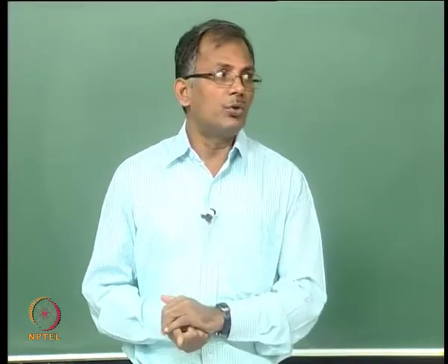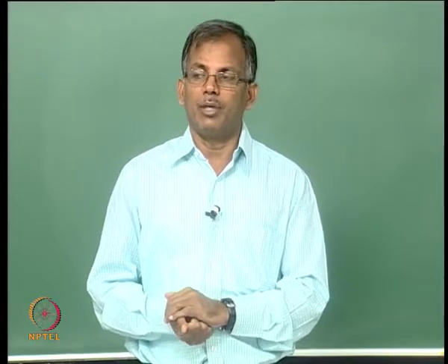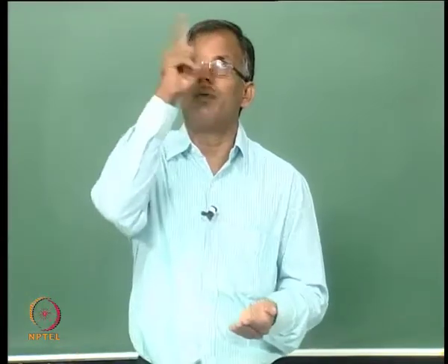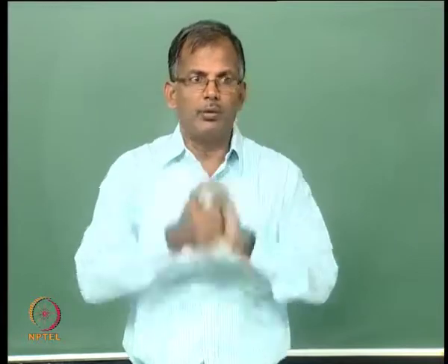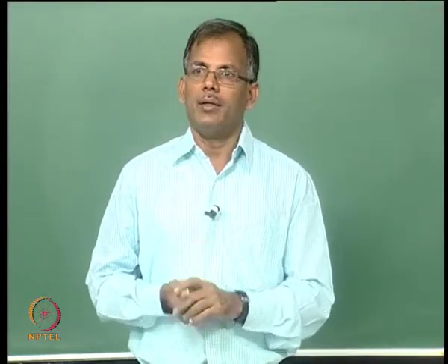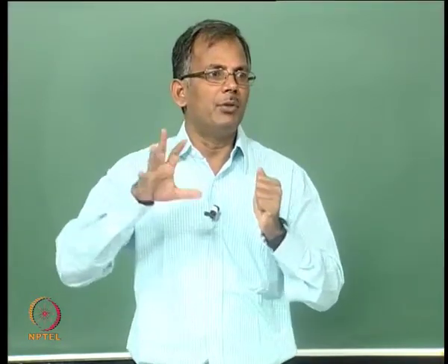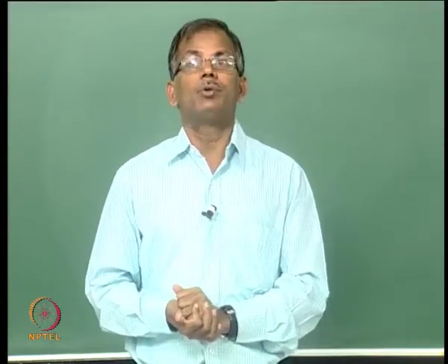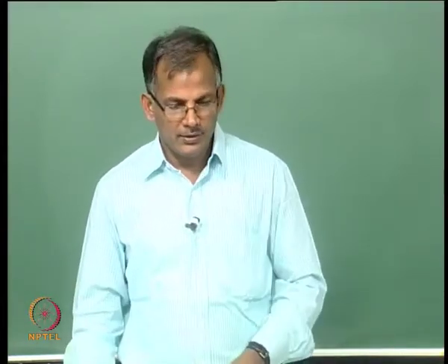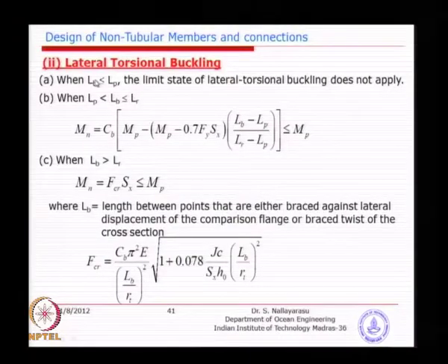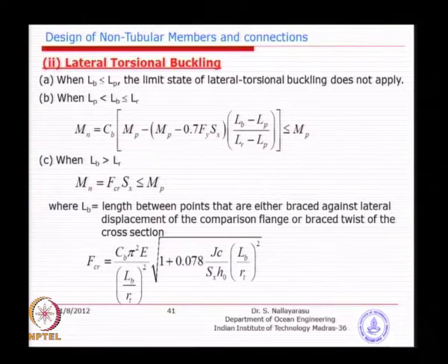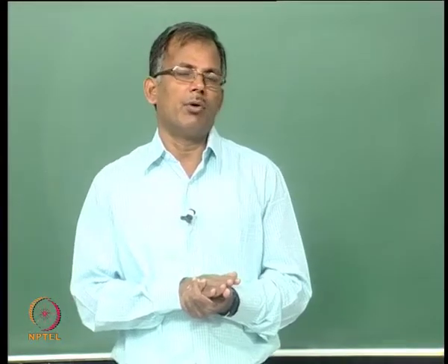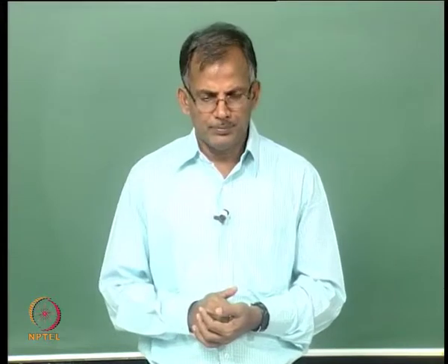That will be the case in most of the deck structures in offshore, because you put one big deck plate, like a floor plate, and weld the floor plate to the beams. So what will happen? The floor plate will not allow the beams to rotate. So in most cases you will see that this will be very small. Where will it be bigger? In cases where you have open sections, there is no floor, but maybe an open grating, the open deck floor, then you will have such kind of problems.